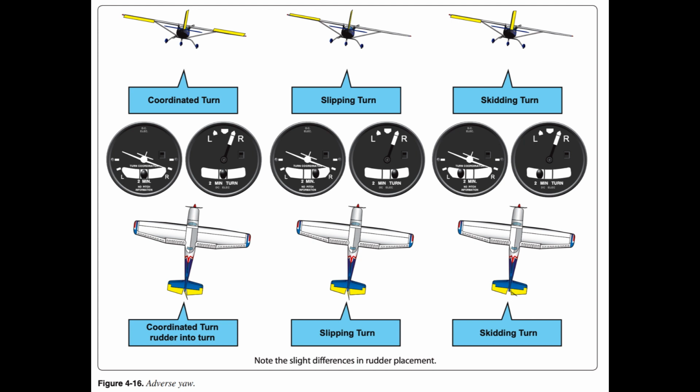its gross weight. When designing an aircraft, it is necessary to determine the highest load factors that can be expected in normal operation under various operational situations. These highest load factors are called limit load factors. Aircraft are placed in various categories, i.e., normal, utility, and acrobatic, depending upon the load factors they are designed to take. For reasons of safety, the aircraft must be designed to withstand certain maximum load factors without any structural damage.